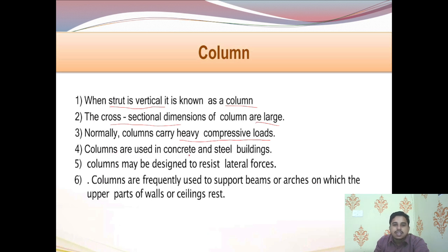Columns carry heavy compressive loads, because of this enlarged cross-sectional dimension. Columns are used in concrete and steel buildings. Columns may be designed to resist lateral forces. Lateral forces means horizontal forces. Columns are frequently used to support beams or arches on which the upper part of walls and ceiling rest.